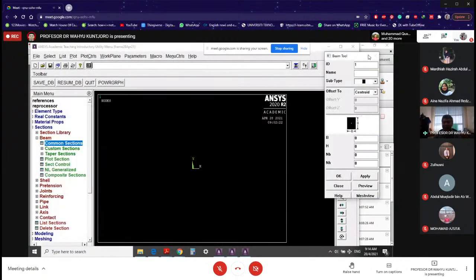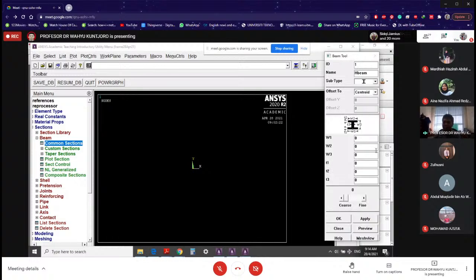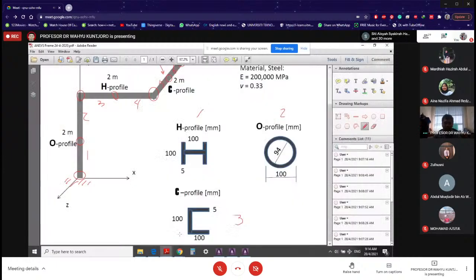All right, I find it. Okay, so I'll name it HB. Subtype. Under that, that's what we want to have. And then the dimension is as what we have over here. 100, 100, and thickness as 5.